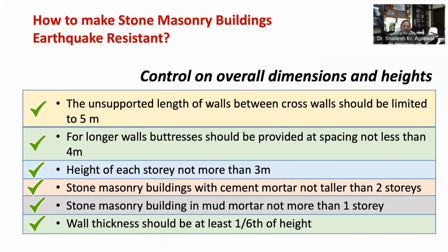Although this type of stone masonry construction practice is deficient with regard to earthquake resistance, its extensive use is likely to continue due to tradition and low cost. But to protect human lives and property in future earthquakes, it is necessary to follow stone masonry construction as I have described in this tip, especially ensure proper wall construction and ensure proper bond in masonry courses for seismic zones 3 or higher. Also, the use of seismic bands is highly recommended.